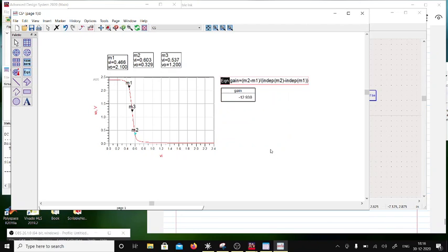Let's express this in dB. This would be gain in dB, and I forget about the sign. If I say the phase shift is 180 degrees, I will put a minus sign here, and then do 20 log of this, so 20 times log 10 of this number.